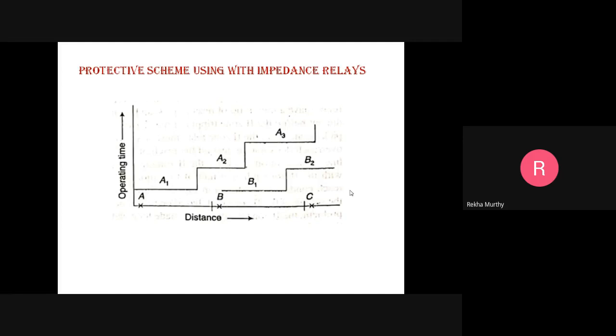So this is about how exactly you're going to protect the fault with this scheme. So make sure here we are providing 80 to 90% and here it is 80% and here it is going to take up a small amount of 25%. Okay. So now let's move on with the next part, that is the connections of the impedance relay.